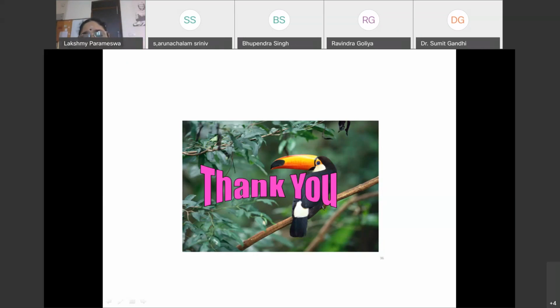We may also have to consider the ponding effect and other effects if you have long span bridges. Then with respect to wind, for special bridges like cable-stayed bridges, we go for wind tunnel testing.